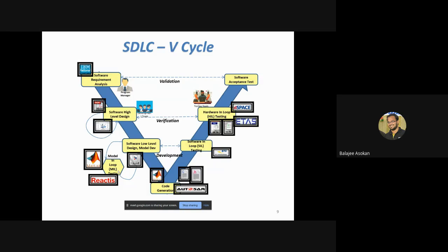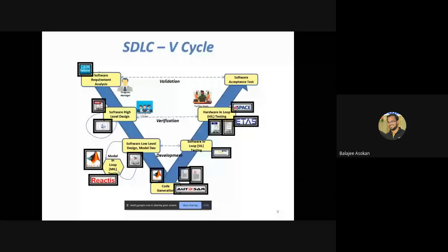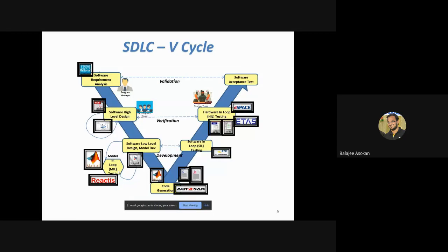When you're talking about automotive software development, the ISO number that they use is ISO 26262 standard. This is what all the OEMs, tier 1 suppliers and companies have to adhere to while developing the control algorithm software for automotive applications. This tool does a background check for every block and every subsystem, verifies its properties, and also verifies the C code that is generated. So this model advisor report does it.